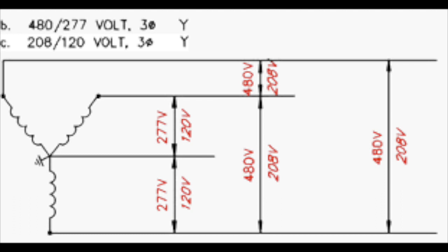And you might be thinking, I like to know why things are the way that they are. I'm somebody that questions things and gets to know the meaning and the source. And you might even look at that number and go, really? What is that? Why 208? Why 277 and why 347? Those seem like odd numbers to me. And the answer is that it's mathematically perfect. It has to do with triangles.